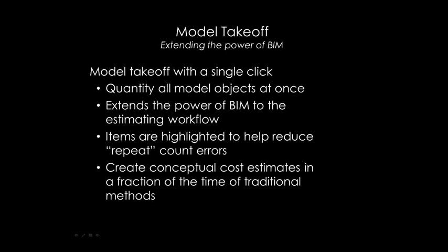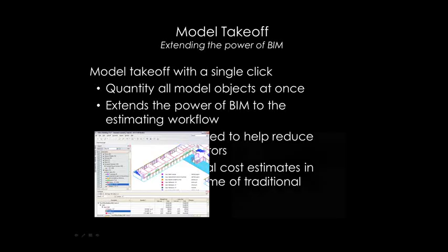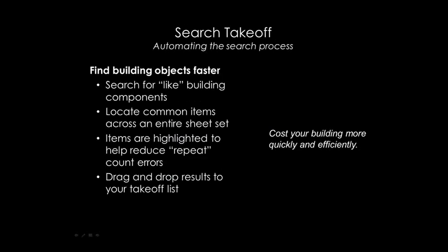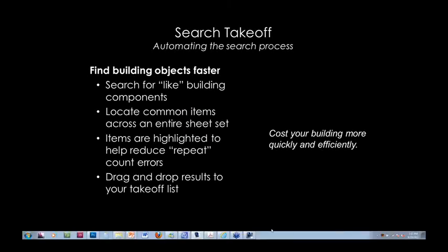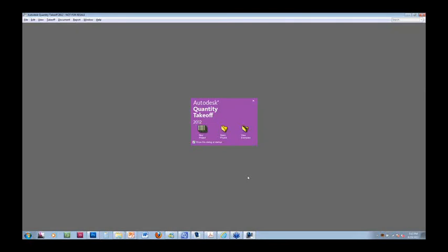It's pretty simple. Again, the good thing about using a BIM model is that you can do a single-click model takeoff, which maps whatever you click on, highlights the whole thing that is based on the same or a similar parameter, and then automatically maps it to an assembly or an item that already has a value and a way of quantifying the object. I'll actually skip this. Let me show you the takeoff, because it's a lot easier when you see things than when you just mention it. Here, quantity takeoff is very simple.